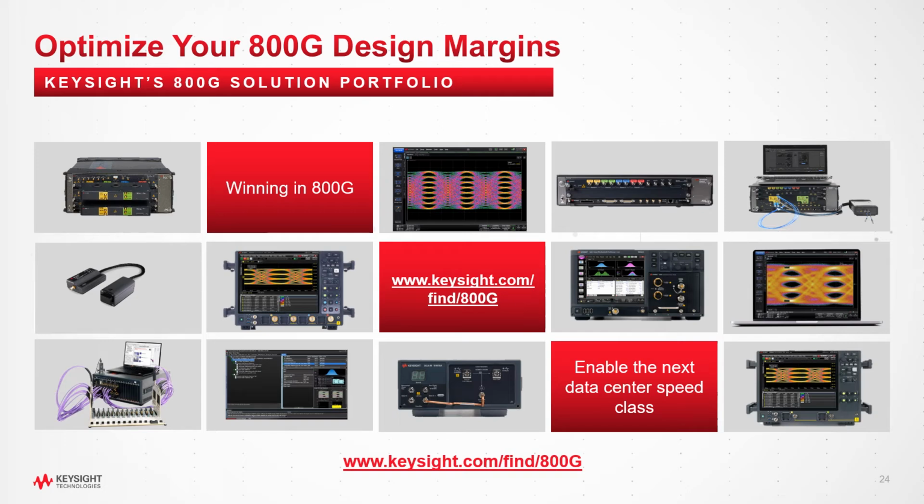Talking more about the parametric test for 800G, photonic integrated circuits, or PICs in short, will allow the next generation 800G networks to yield higher capacity and significantly improve power consumption and manufacturability. One needs to test optoelectric wafer-level systems, which would involve electrical measurement of sheet resistance and capacitance, and optical measurements of attenuation and responsivity, to characterize the PIC material and structure quality. Keysight Technologies photonic on-wafer test solution will help characterize the user's PICs and optical devices.